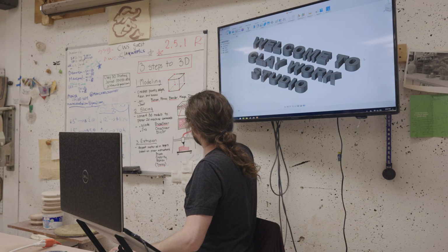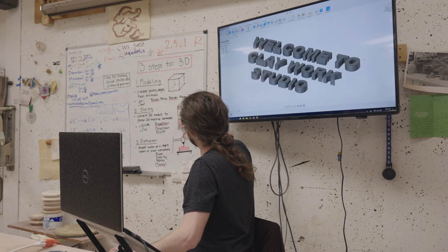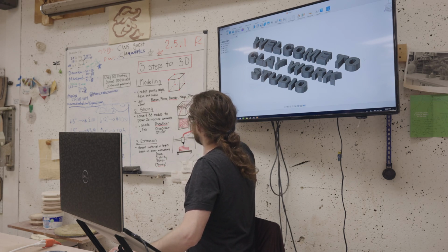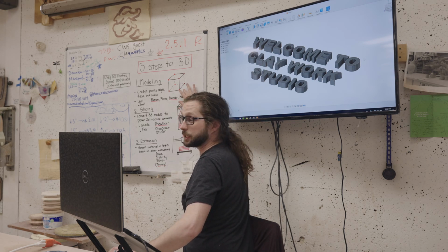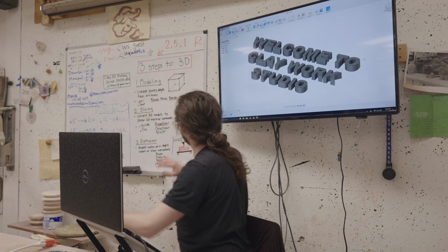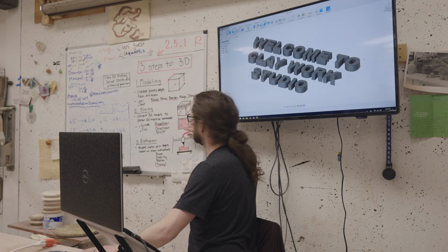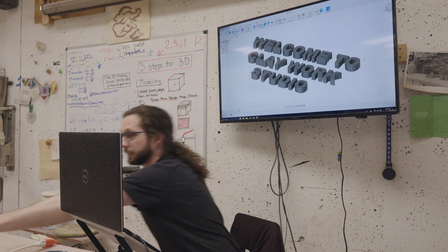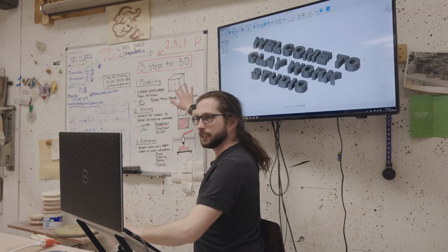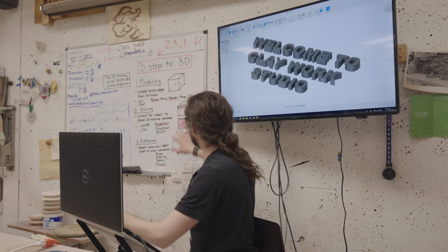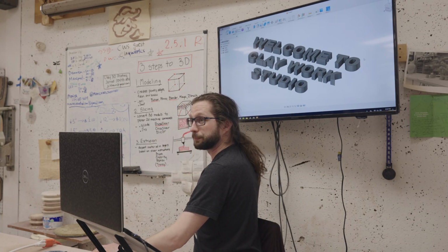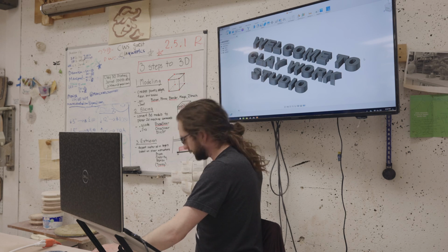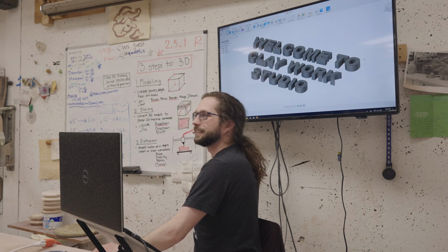So there's a lot of settings that you can do inside the slicer to change its behavior in this, right? So I could model a cube, but maybe I actually want it to be a vase, and it's in the slicer that I can tell it, just print the edges of this thing, don't worry about printing the middle. So for example, almost all of these models like this were modeled as a solid, and then to make it into a vase, I actually changed that in the slicer. So you got to know both, so you know what you can handle, what you can punt to the next.